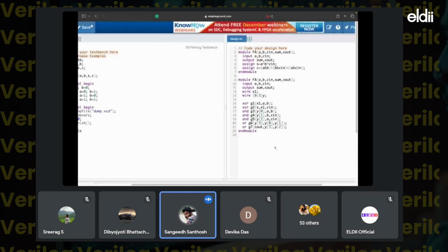Means I have taken a symbol of a full adder circuit. Even in that full adder circuit, we are using how many gates? 2 XOR gates, 3 AND gates, and 2 OR gates. So writing code for a simple full adder is a lengthier one. So what will happen for an 8-bit ripple carry adder or 16-bit ripple carry adder? That will be a tedious task. So in that case, we go for data flow modeling. That is easier as compared to gate level.